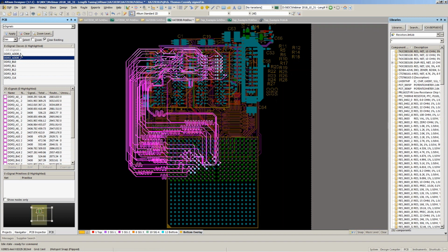Of course, as you can see, when you're doing your length tuning, you'll do the first one here, get that the way you want it, and then do the second one. Any changes you need to make, you of course want to use the signals between the chips. You don't want to modify the original signals, or you'll mess up your first one. And like I said earlier, if I had more than 2 chips, if I had another chip over here, I would have had address 3, and it would have added that little segment on, and so on and so on.